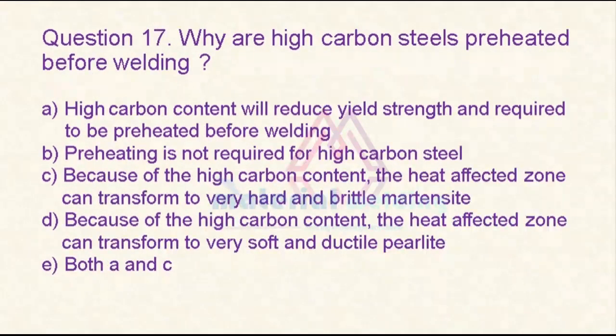Question 17. Why are high carbon steels preheated before welding? A. High carbon content will reduce yield strength and is required to be preheated before welding. B. Preheating is not required for high carbon steel. C. Because of the high carbon content, the heat affected zone can transform to very hard and brittle martensite.